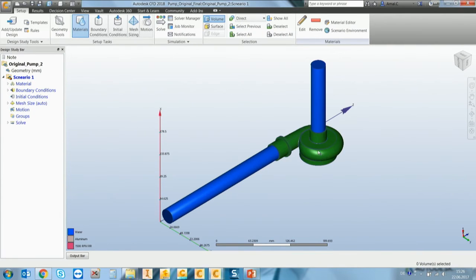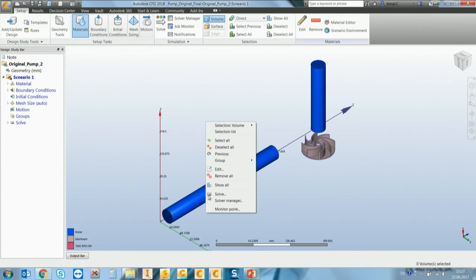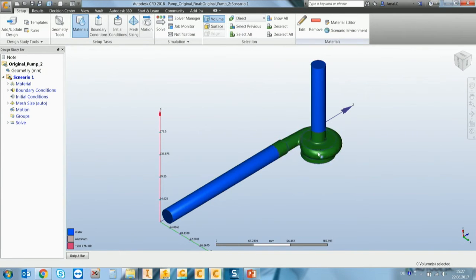And then you select your solids, and then choose also the type of solid material. You have also a rich library. You can even select a human if you think that it's a good idea to simulate it in this kind of analysis. And yeah, glass, a lot of default materials. You can also create your custom materials, by the way. So I'm going to put it as solid.